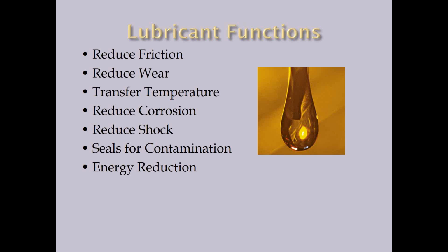Lubricants create a seal for contamination. One of the reasons in my training, I train people when they're greasing electric motors. Maybe you're not greasing an electric motor for 100% the reason of lubricating the bearing, but it keeps contamination out.